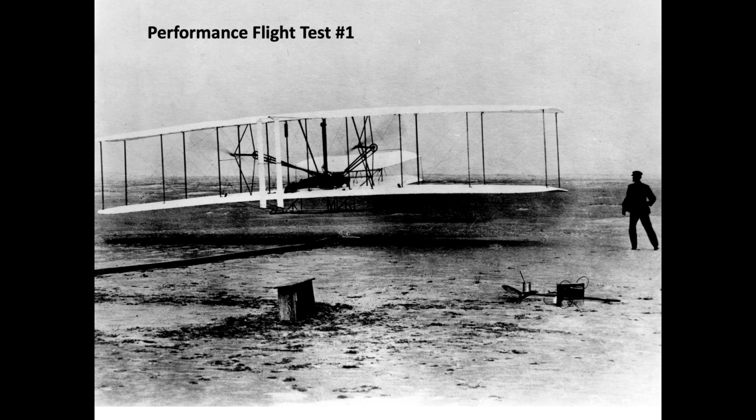So let's benchmark, go back to our first case study, performance analysis of the Wright Flyer. We don't have a lot of data about how well this aircraft actually performed on its first flight, other than its flight only lasted 12 seconds and only covered 120 feet. Even with these rudimentary numbers, however, we can at least determine what the average velocity was over that flight time, and then go back and look at some of the design parameters of that aircraft, for example, the weight of the aircraft, the wing area, the wingspan, some drag estimates, to be able to determine some more details about the overall aircraft performance.